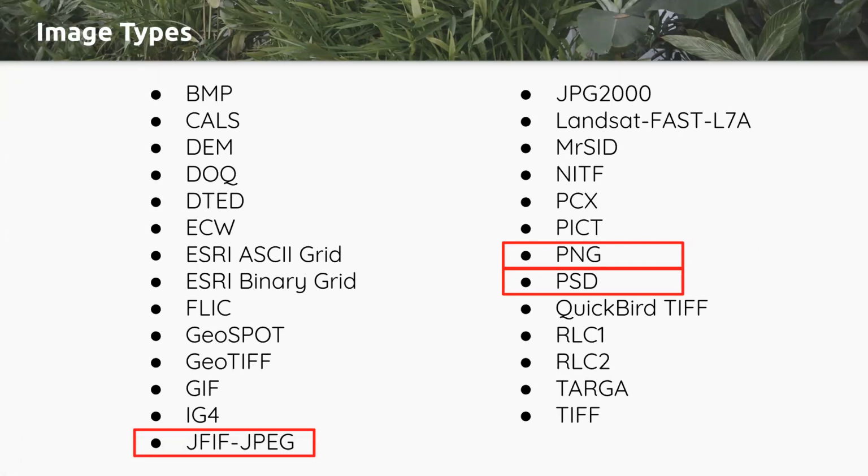Now, you're going to notice also, well, where's PDF in this? PDF is actually not an image type. It is a file format that is accepted through CAD. I am tagging this on to the image webinar, because it is such a common practice to use a PDF as your base image. It's just technically in a different section. Even if you were to browse the Autodesk website and find supported image types, you will not see PDF because it is a supported file type and can be used that way.